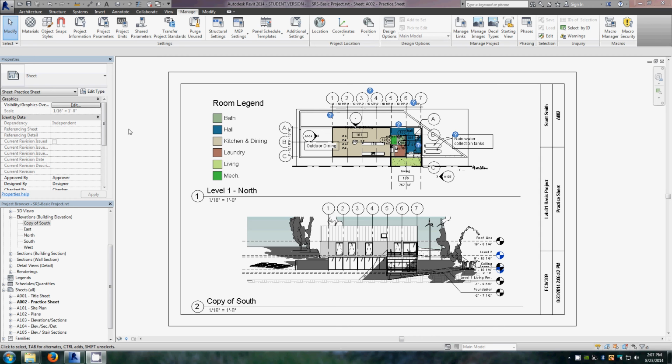Okay, so this is what I want to see on your sheet that you're going to print and hand in for credit. Show me that you've made a title block, that you've created a north section, put it in, that you've changed the wall to the brick and shown that in elevation. Make sure that your name is on here and that all these other labels are correct for lab and the practice sheet and the name here, ECIV 309, and the timestamp. And you should be ready to print now.